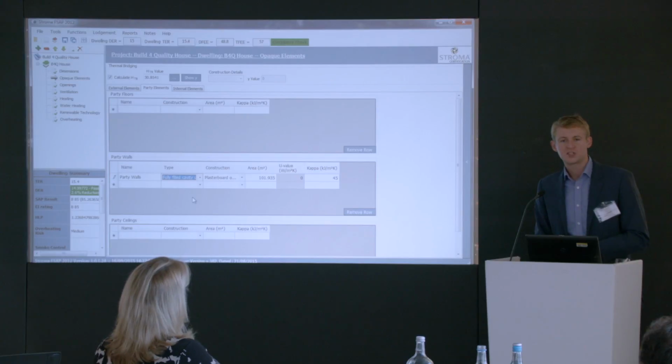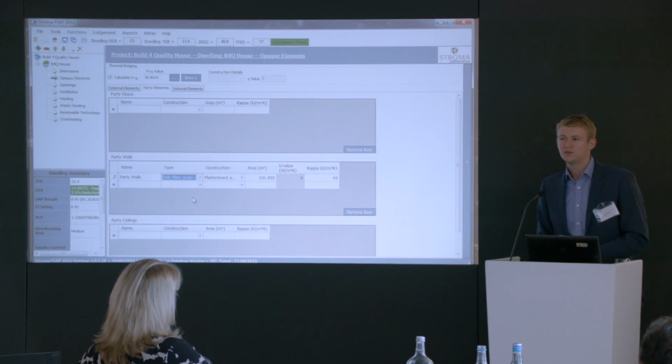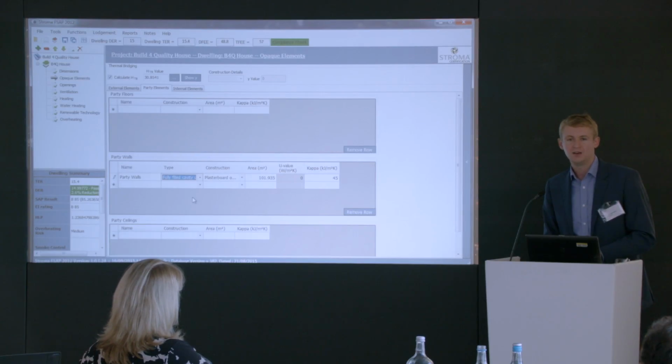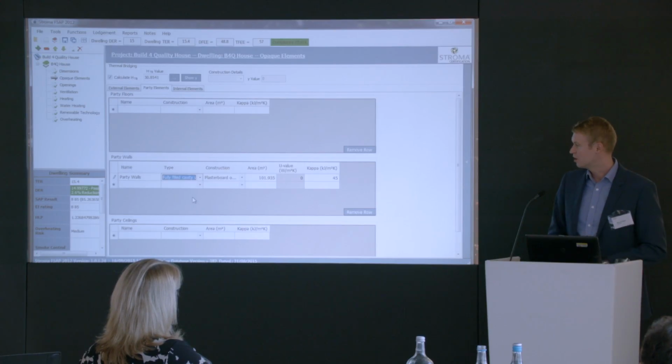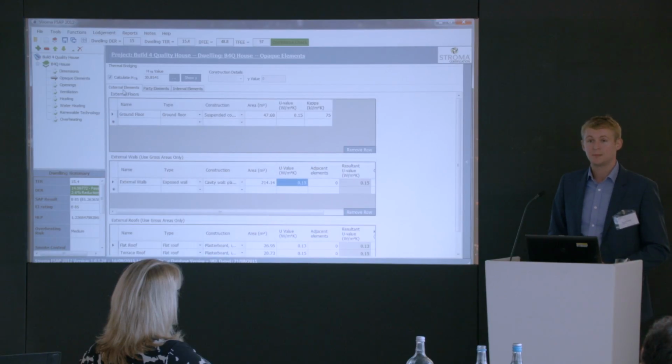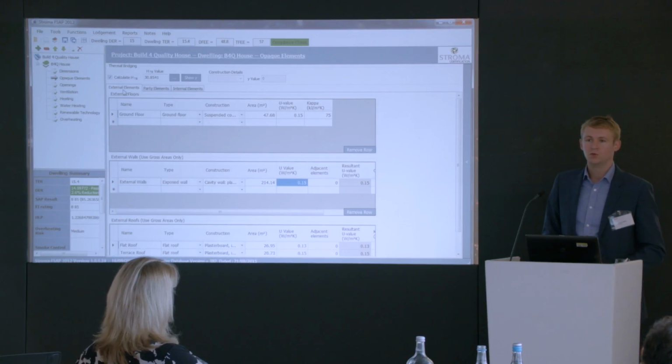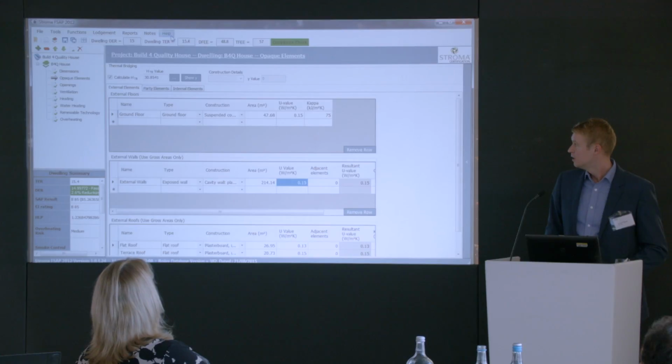I think a point up for discussion at the moment is whether you consider there will be any convective heat loss in party walls in apartment blocks, where you might actually have a concrete floor above that party wall. I think that's an area that's up for grabs at the moment. So that's party wall heat loss. That is a big influence and something we need to be looking at, and obviously balancing Part E as well. I know quite a few of the robust details do allow for full fill insulation there.